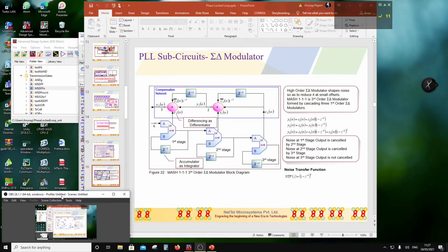Okay, so I just brought this up here. So what do we have? We have these carry bits, right? These carry bits C0, C1, C2 are going to go through this network. What I need to do is, first of all, subtract, but subtract a delayed copy of it. So as we were adding a delayed copy with Z minus here, we'll be subtracting a delayed copy.